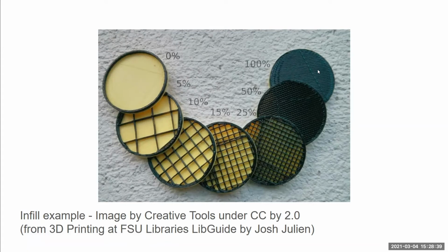But if you go for 100% infill, that's a really heavy, dense object that uses a lot of plastic and takes a lot longer to print, because all of these different lines have to be drawn by the 3D printer, because it doesn't print in large diameters. It prints just whatever the diameter of that line is. The opposite is true with 0% infill. If it's completely hollow, it's kind of a weak object, so it only has those thin little plastic walls, which is why you can have various different percentages of infill depending on what you want that part to do.